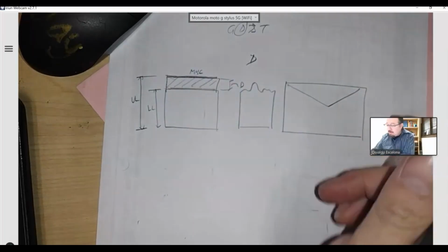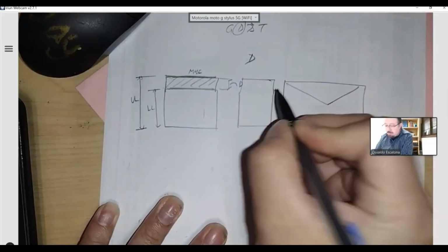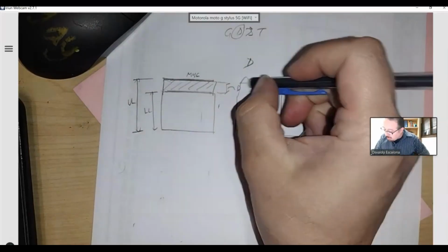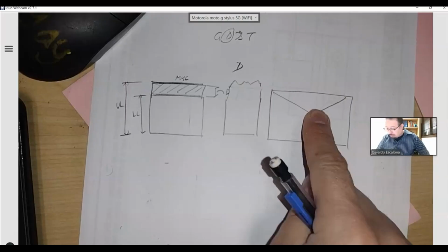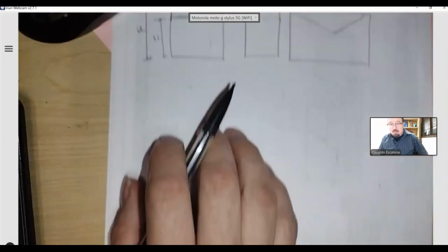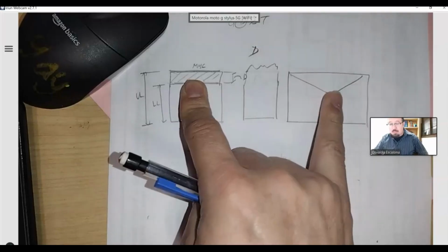But if my part is all the way at the top and has any type of form variation, any surface variation, it will not fit into my envelope, which will make it fail my inspection process. That's why they call it the envelope principle: perfect form at MMC. When your part comes at MMC, it had better be perfect, because otherwise it will not fit in your envelope.